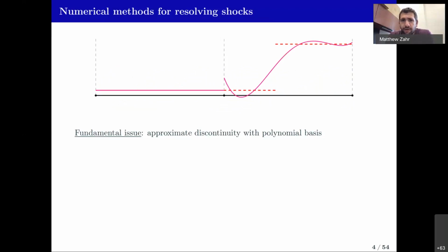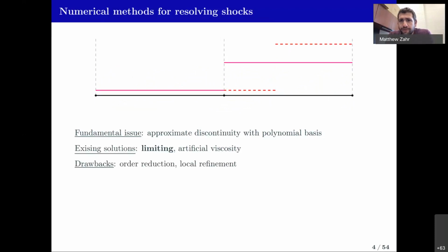So this is a problem that's been around forever in CFD. The way that people deal with this is there's a number of different ways. One is that you do something called limiting, where you say, I don't want to allow all those high order oscillations, so I'm just going to crush them and reduce this to a first order approximation here. And that's fine. It addresses the overshoot undershoot issue, but it's obviously a pretty crappy approximation still. So you have to add in some mesh refinement near the discontinuity, and you can get a decent approximation. The downside of this is that we just went the opposite direction of model reduction. Instead of trying to make things cheaper, we made it more expensive to have to refine in these regions.